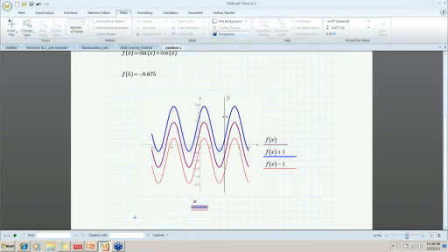Okay, and in traditional Mathcad, we could put markers on plots, but we could only have 2 at a time vertically and horizontally. So that limit has been lifted, and now we can have more than 2. I believe we can have 8 markers horizontally and vertically at the same time on a 2D plot. So you can see that it's very easy to interface with a 2D plot. So we have the traces category here. We have the markers category, which we just talked about, the styles for your traces, the color, the thickness, the symbols, things like that.